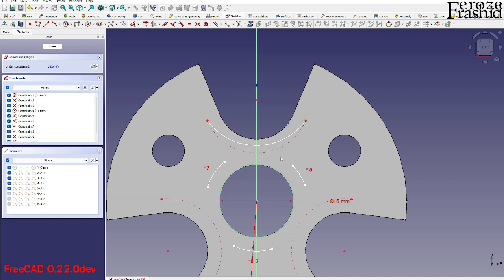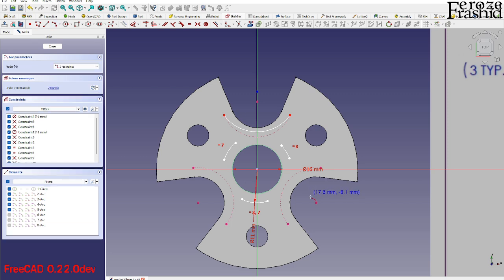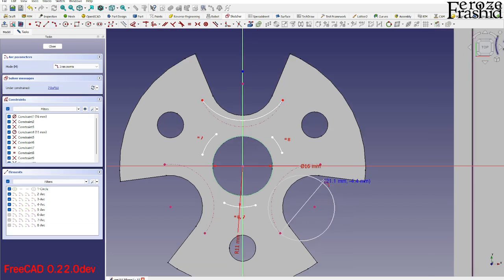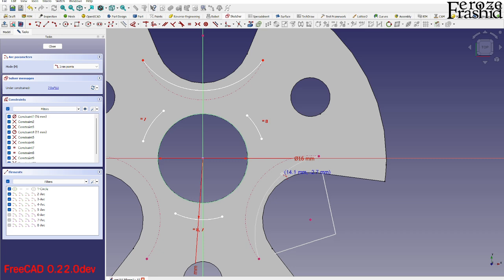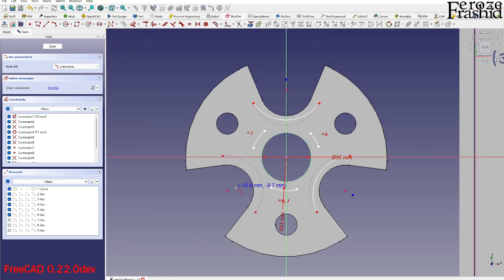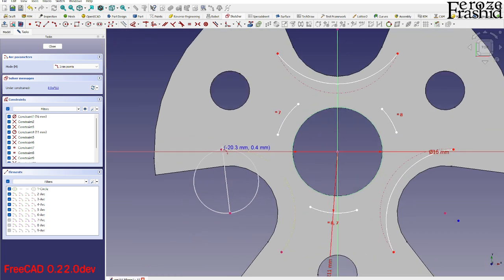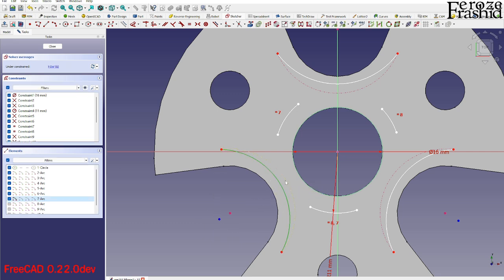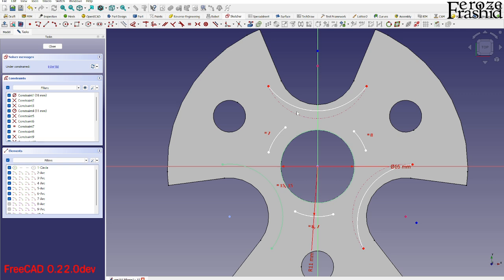I'm going to go ahead and make this like that and come back later on to fix them. So this constraining in arc to arc has been an issue so far in my experience. I don't know if it is a big deal, but so this is the most effective way. Come back to make them equal, and that won't give you any trouble.